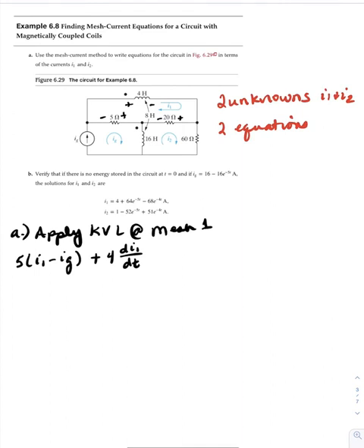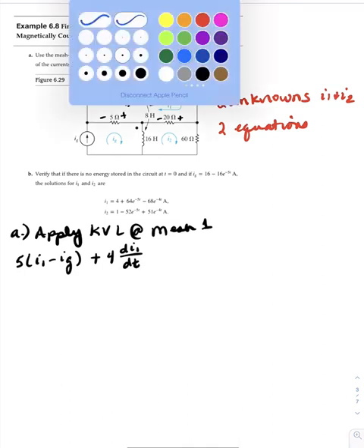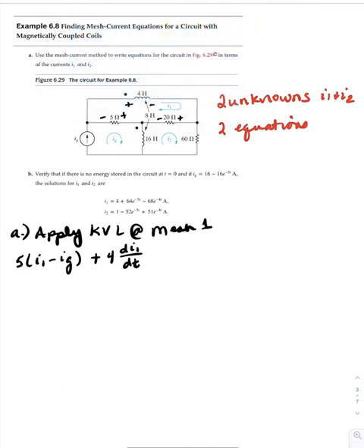Now we need to know, is it plus or minus the mutual inductance? The 16 Henry inductor is causing a mutual inductance of 8 Henrys with the 4 Henry inductor. To choose our sign convention, we determine the polarity of how we're going to write this.